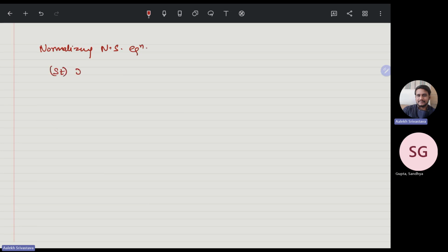this is the coefficient into del V star by del T star, plus V star dot this term into V star, is equal to 1 by Euler number into the pressure star term, plus, if I write the gravity term separately, 1 by Froude number square and the gravity term, plus 1 by Re into the Laplacian of velocity.